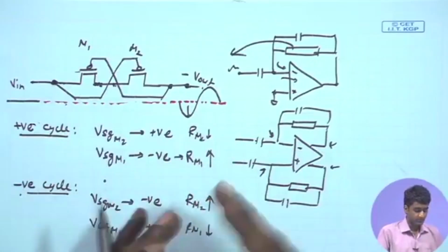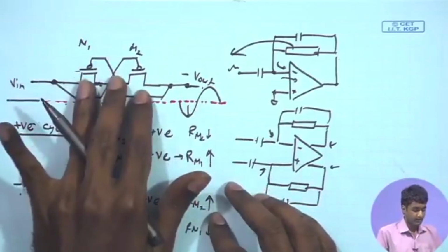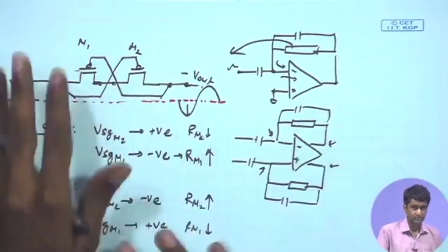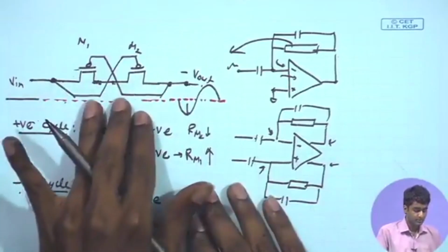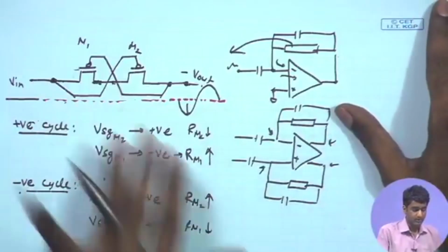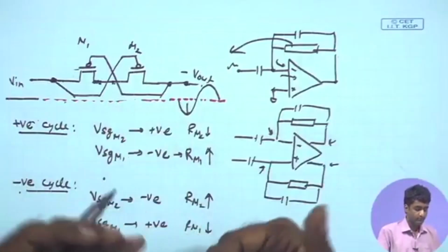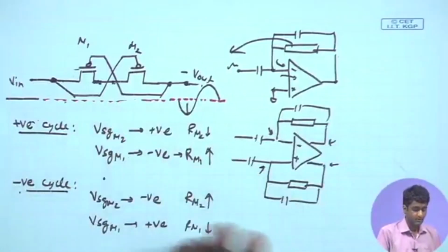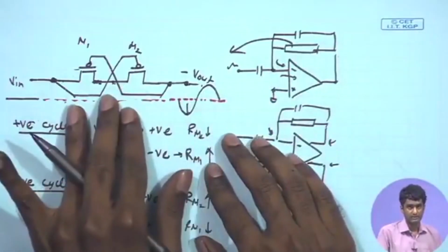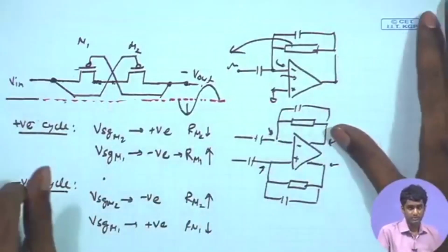And likewise, from a process point of view also we can have significant shifts in the Vt. It can be a time dependent shift as well, which can shift the characteristics. So, we want to have some kind of tuning options which can be used to calibrate these values either automatically or one time. The preferred way may be to have automated calibration, so that once you have deployed the chip for its normal operation, there also you can have some mechanisms of sensing it, and then again using the tuning options for adjusting the values. So, we will not discuss all those, we will just discuss how we can implement one possible scheme for tuning.